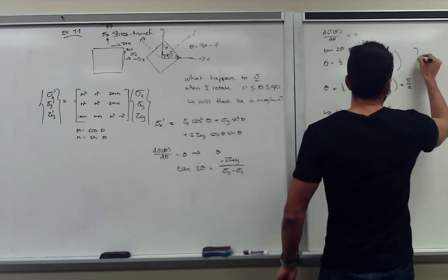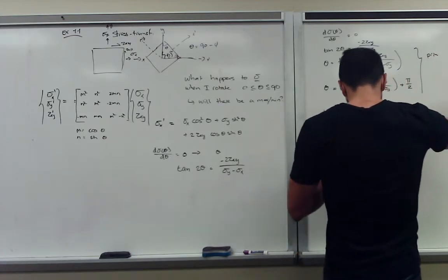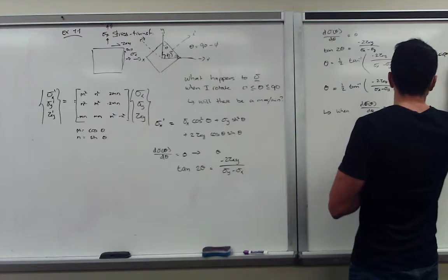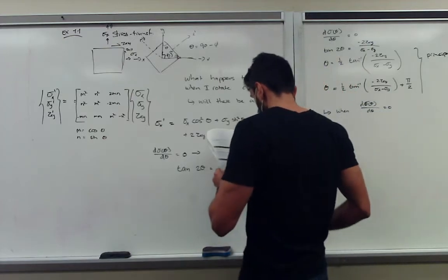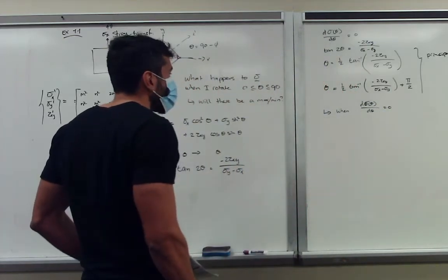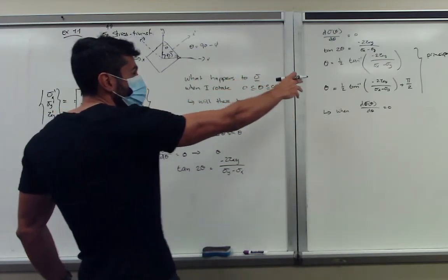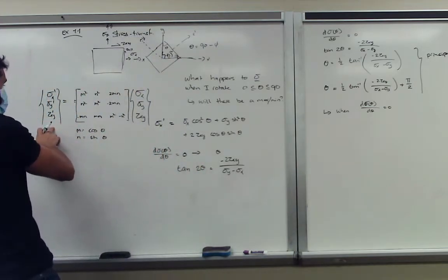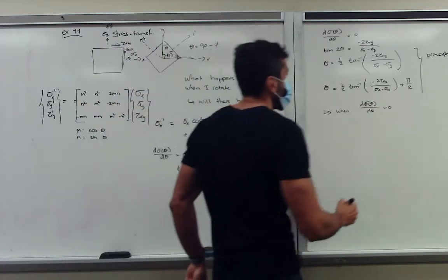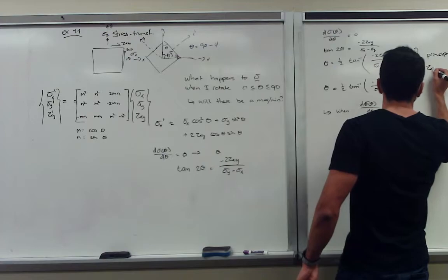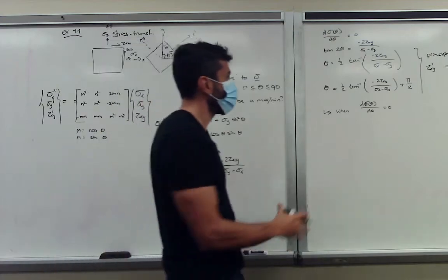These two axes are very important because we call them principal axes. If I plug these thetas into our equation and get our transformed stresses, we notice that the shear stresses disappear. So we only have two stresses acting on those planes.